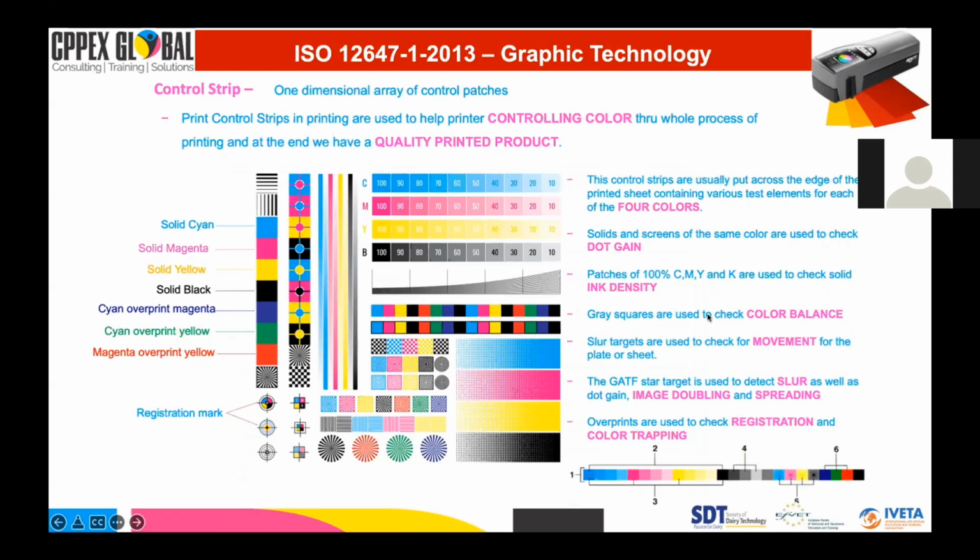All of our press sheets should and must have a control bar for Flexo. The FTA has some very nice samples that you can get. Nearly every prepress company has these. Unless there's something in our press sheet to measure, really we don't know, we're just eyeballing it. So without something in it, I know it takes up some real estate, but it can be trimmed. Unless we have something to measure and monitor, really we're flying blind.